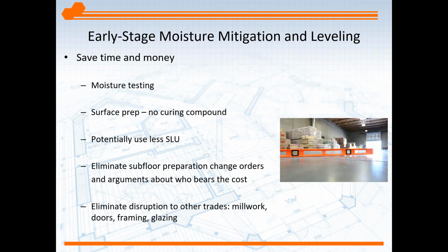Once concrete is placed, it can be perfectly flat within the first few days of installation, but weeks, months down the road, as that slab dries, it will curl and deform at joints and perimeters or edges. And that curling can create a gap of several inches, as we see in the slide here, underneath that straight edge. So by applying moisture mitigation early, holding moisture in that slab earlier, the amount of curl or deformation is greatly minimized, again using less product for leveling down the road.